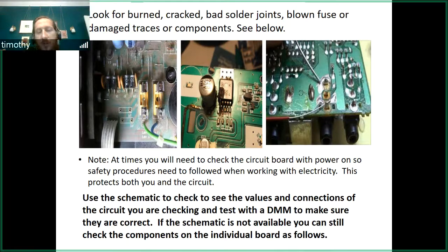But most of the times electricity is so fast that it'll get up to temp real quick if you have a short in your circuit, and you'll hear it just pop and you'll smell the smoke. So this is one of the reasons you want to double check before you ever apply power. This is another one where you can see the burnt area up at top.